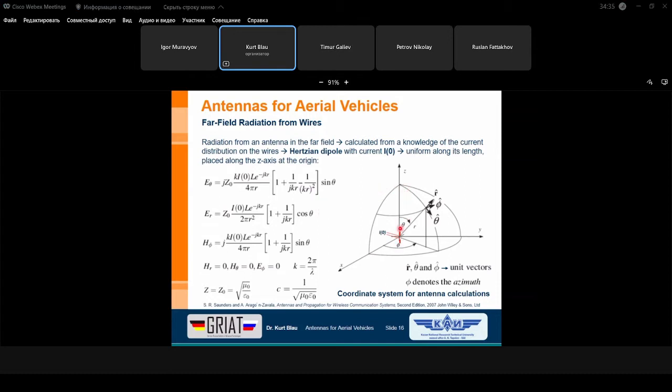Again, you see the dipole, it's directed exactly in the z-axis. And this means in all planes which cut the z-axis, we have this theta-directed E-field component, and perpendicular, meaning in the phi direction, we have no E-field, but we have an H-field, and this is visible here. This is this part. It means at each field point we have two components.